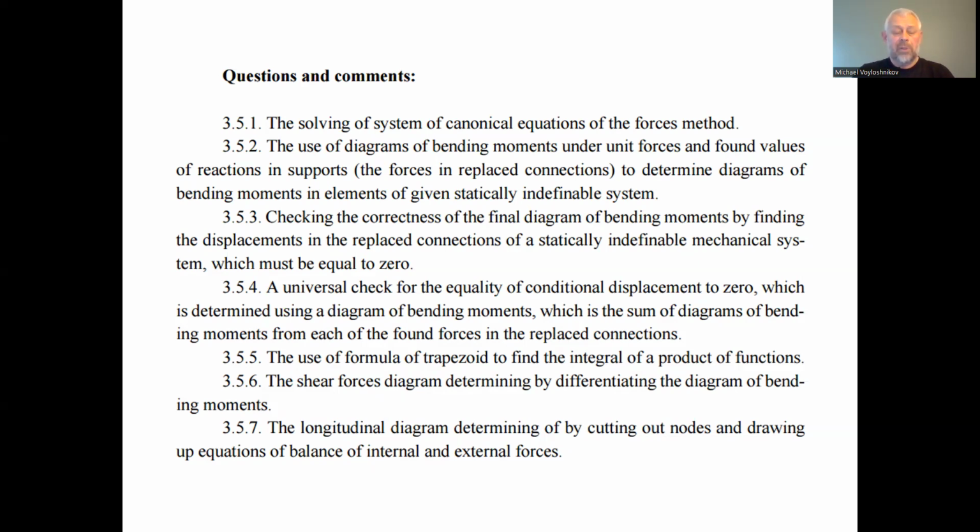But even more than that, instead of checking the displacement in two or more directions of the cut-off supporting links, according to the degree of statical indefinability of the assigned system, we can as well consider one general displacement.